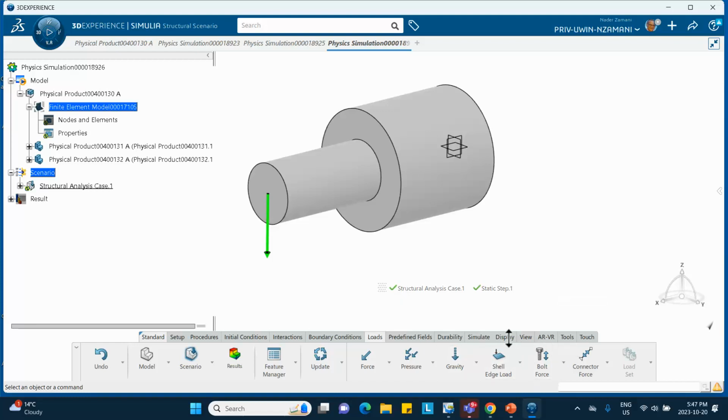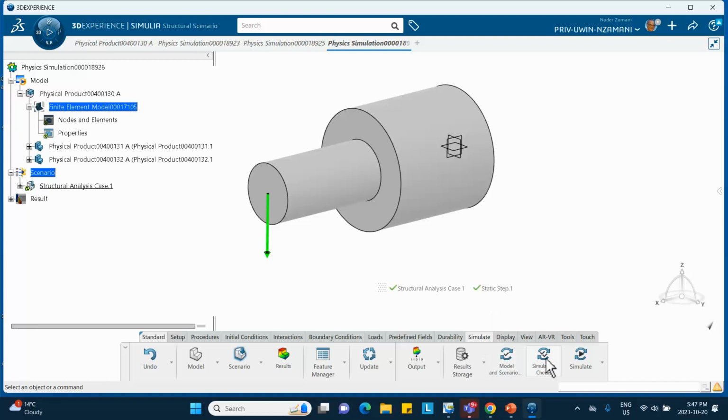So I'm not going to check these two. I'm just going to literally run it. It will bomb out because these two pieces of an assembly, they're not talking to each other. They don't know that they're attached to each other. When you do a problem with assembly, you must create interaction between them. They can be contact, they can be tied, and they can be other things, for example. We did not do that. After it bombs out, I will come and do that for you, okay?